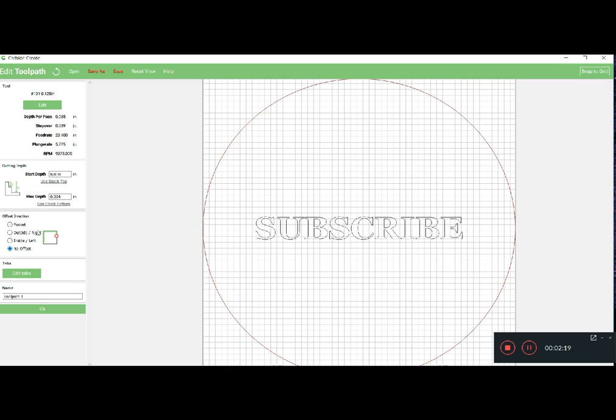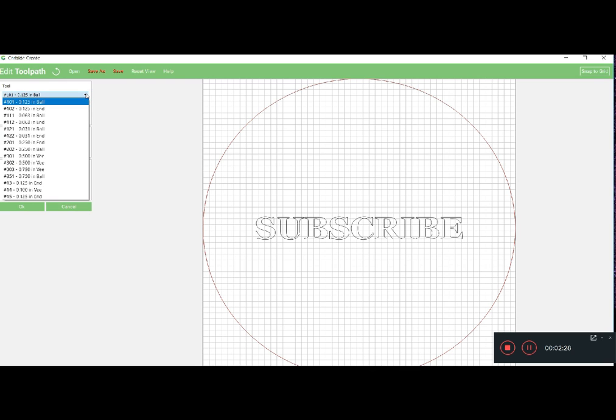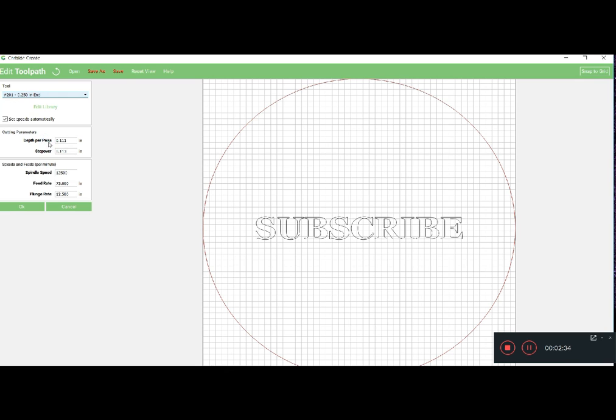We're going to go no offset, and then we're going to switch the bit, because this right here, we don't want that bit. It's a ball bit. It's good for 3D carving and so on. We're going to go with the bit that they actually sent us with the machine. It's the 201 1/4 inch end mill. So we're going to click on that, and they're going to see a couple different options.